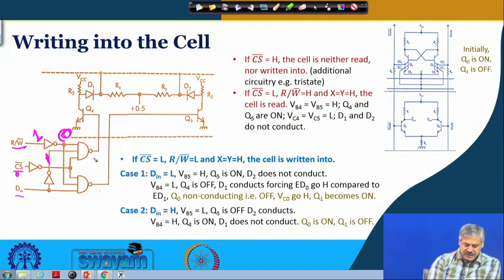So this 0 will generate for this NAND gate output A1 and it will generate output, this is 1. Please understand. Okay. So chip select is 0 and read write bar input is 1. So what we are having? We are having a 1 1 over here, irrespective of whatever be the value of D in. Okay, because read input 1 means this NOT gate output is 0 and corresponding these two NAND gates output will be 1. This part is understood. Okay.